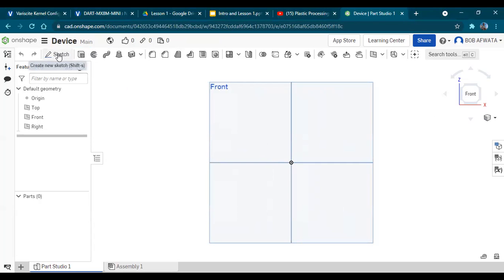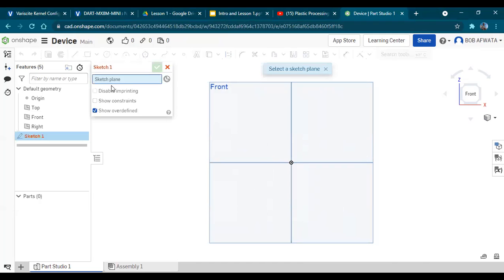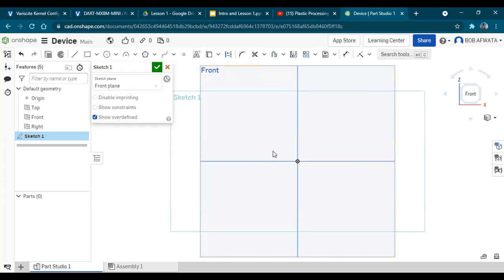Okay, so go up there to sketch, create a new sketch. If you are on Fusion, there is the green part. So sketch, and then you click the plane where you want to print to, and it turns into this 2D view, where you have all these functions. As I told you, it's very similar to Fusion. So I want you to take a line and draw the line.